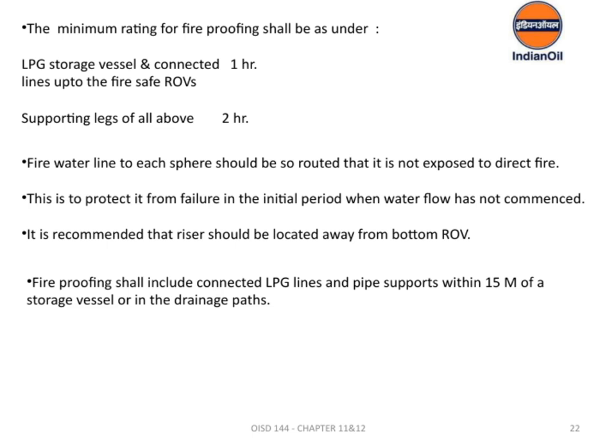Now, regarding fireproofing ratings, the minimum standards are quite specific. For LPG storage vessels and the connected lines up to the fire-safe ROVs, a fire resistance of at least 1 hour is required. For the supporting legs of all these components, a minimum rating of 2 hours is recommended. These measures are vital for overall safety and integrity of the system, aligning with our broader goal of ensuring safety and reliability in our operations.